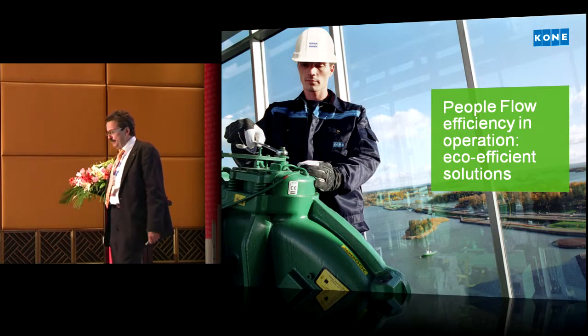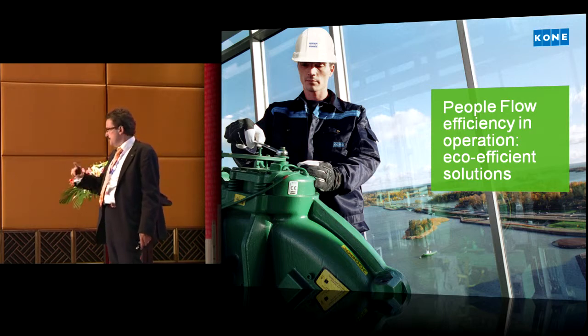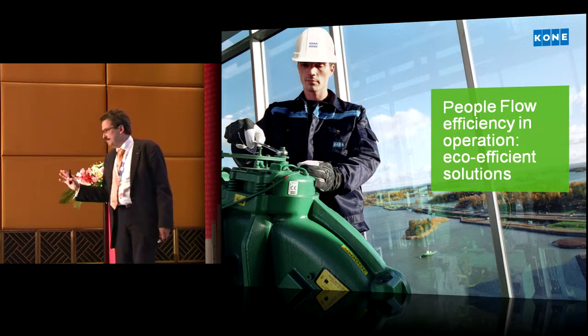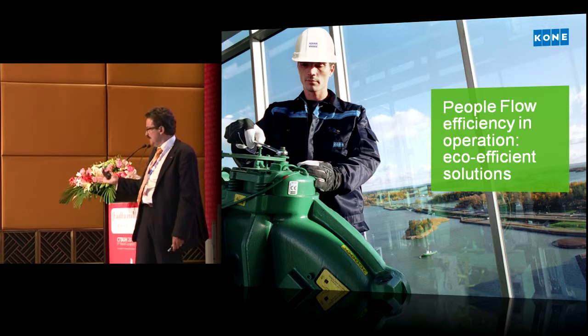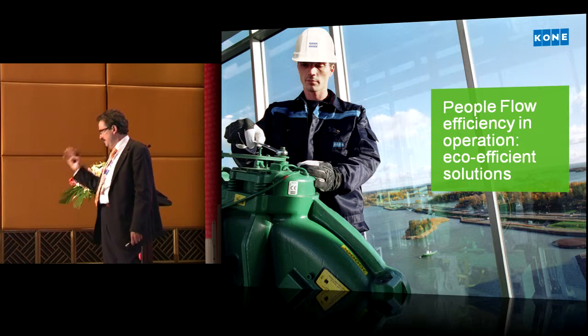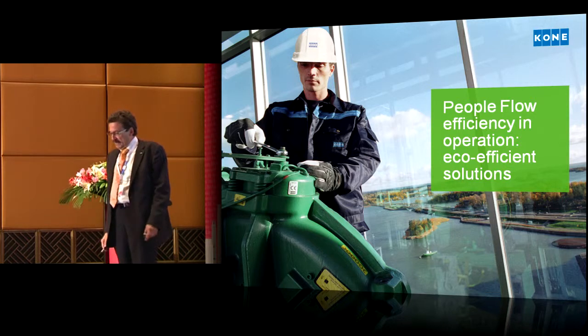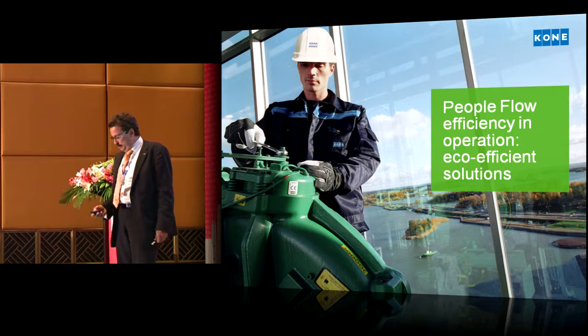Then we go to people flow efficiency in operations. By the way, typically the jump lifts will reduce your construction time by roughly 20%. So if you have a 2-year contract, 24 months, you can finish 4 to 5 months quicker with jump lifts if you have the right amount. It's typically that amount. Then people flow efficiency in operation, eco-efficiency.